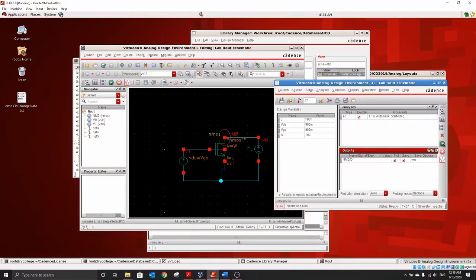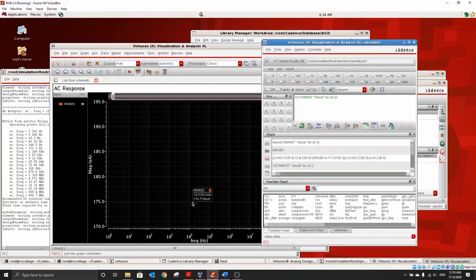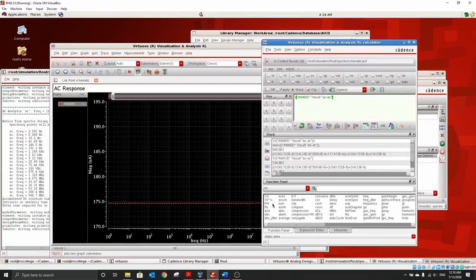The only thing that we have to do is to run this, and the run has created a graph for us which is I by V, where V is equal to 1. Now what we wanted is to measure the output impedance, right? So in order to measure the output impedance, we needed a V by I term, which means that we have to plot an inversion of this graph. That could be done by going to Tools, Calculator, selecting the graph that has been plotted, and going for the 1 by X function and then replotting it.